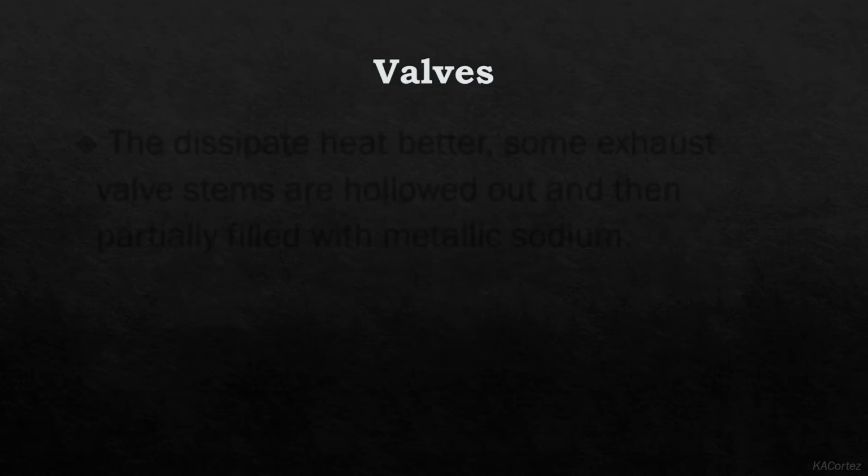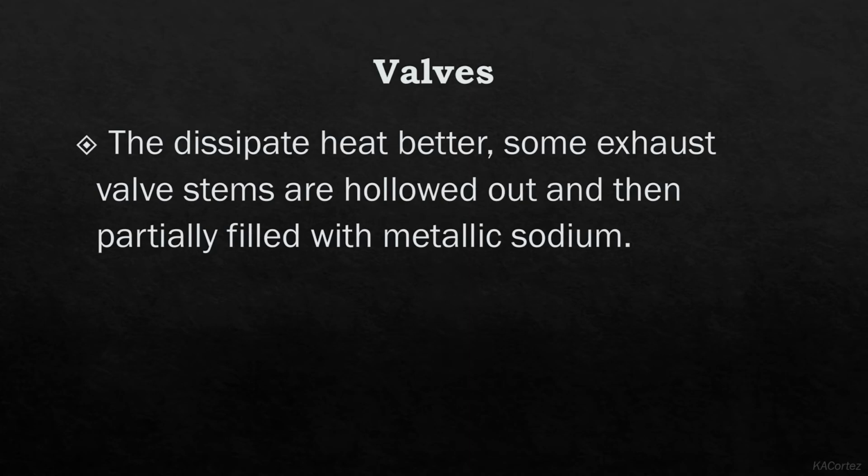Some valves are fitted with metallic sodium. This reduces the operating temperatures during operation. The sodium melts and transfers heat to the valve stem, where the heat is conducted away by the cylinder head.